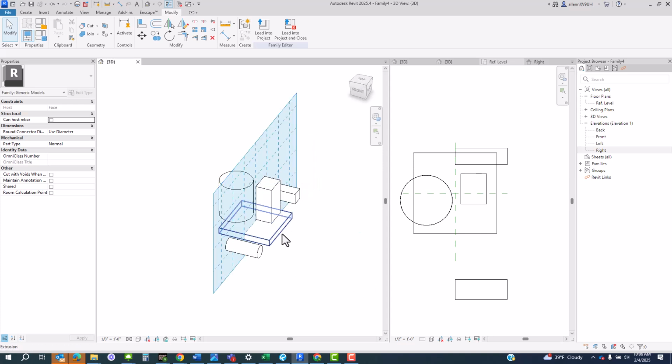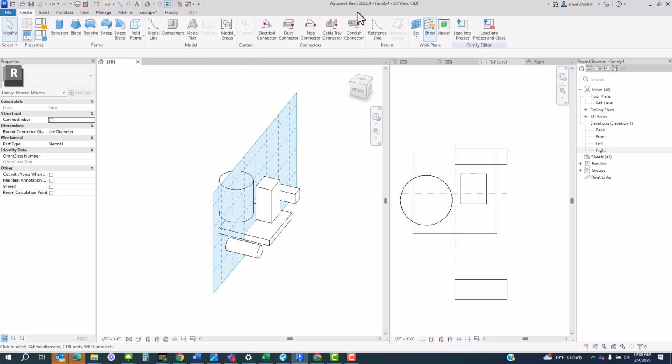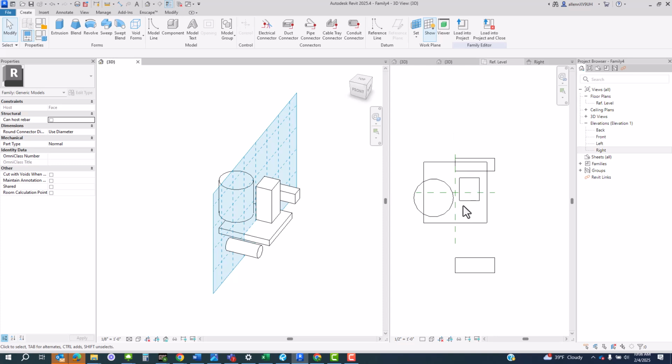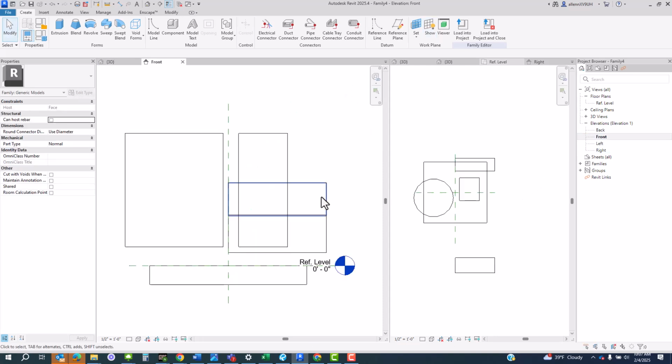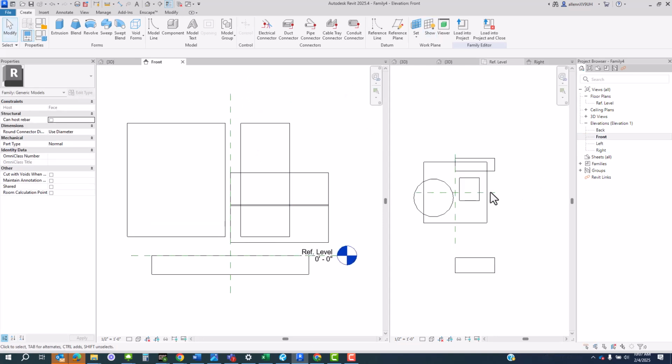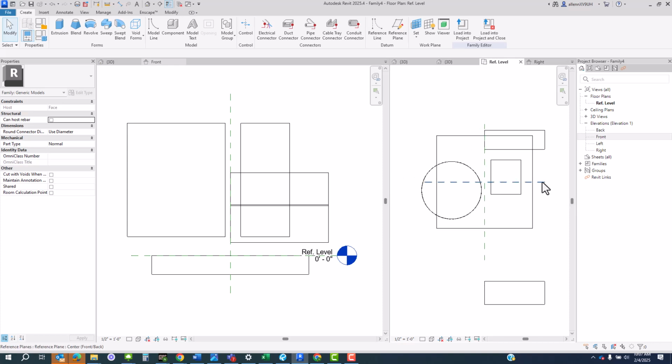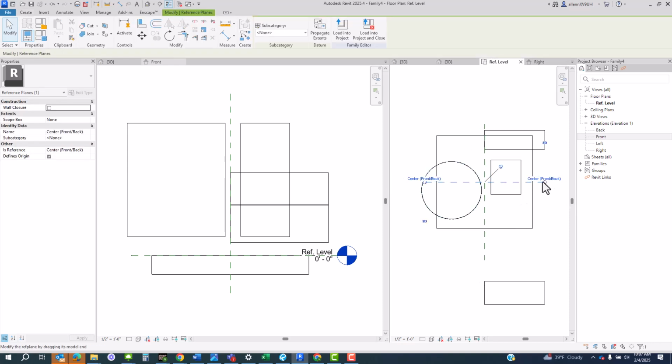Okay, so back over here, we've got two work planes, so of course I could set it in the other direction. And if I wanted to draw on any one of these work planes, I would just go into a view that looks at the piece of paper, if you will. So if I go to the front view, here's the front view now, and that means we would be drawing on this one because now that's got to be the active work plane in this view.